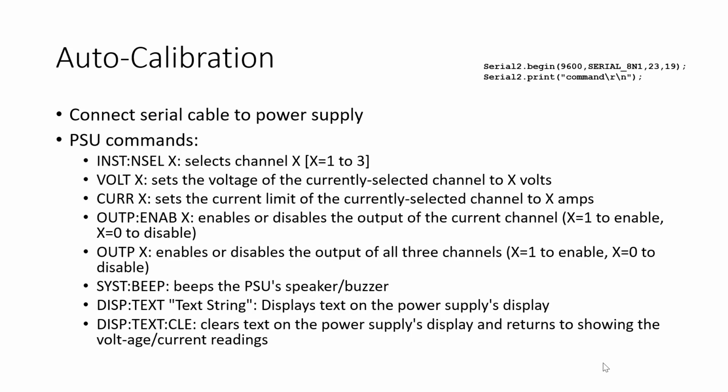The reason it's 0 is because typically you set the voltage when it's not actually on. So you set the voltage, say 5 volts or 12 volts, and you hit enter, and then it says 0. And once you hit the on button, then it'll show you the 12 volts, because it's actually putting out 12 volts. I find these a little confusing for that reason.